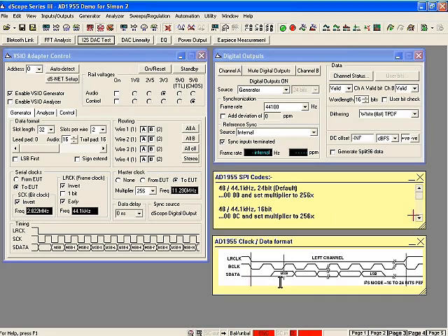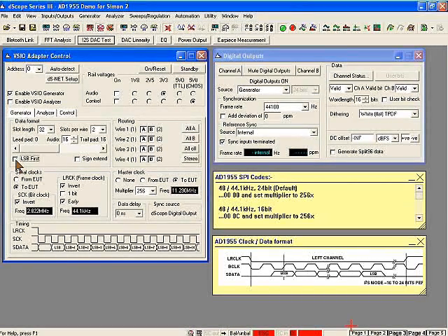So very briefly, let's look at the data. This is set up as most significant bit first, and I have a checkbox here that will change between LSB, or least significant bit first, and MSB, or most significant bit first. And you can see at the bottom here, this timing diagram shows us that updating as we make those changes. The bit clock here is configured so that when the MSB starts, or in fact when any of the individual bits start, we are actually on a falling edge of the bit clock. In other words, the clock is inverted. So if I go to my bit clock here, you'll see that I have checked that option, and we can see the timing diagram update again.